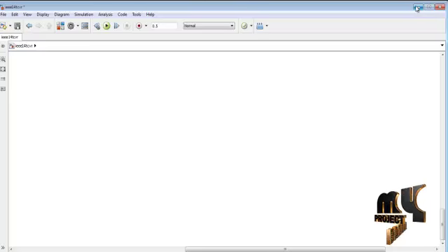In the IEEE 14 bus system, we arrange the elements from the Simulink library browser. In the Simulink library browser we use two toolboxes: one is the SimPowerSystems toolbox, another is the commonly used blocks toolbox. From those toolboxes we get the elements and arrange them as per the given flow diagram. After that, click the run icon, and the simulation will start to run.